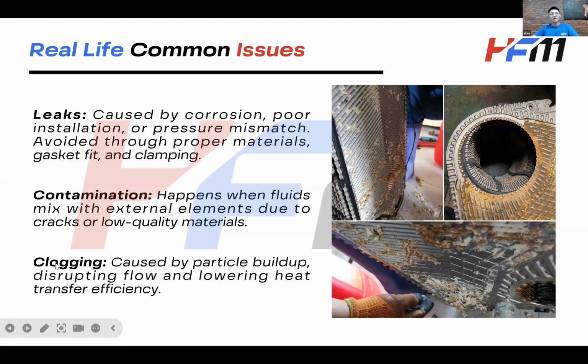Okay, the last one is clogging, and it is caused by particle buildup. I think it is easy to get this point because try to imagine that there are so many different types of products with relatively big particle sizes. They are easy to accumulate in the gaps between heat transfer plates, so clogging occurs.